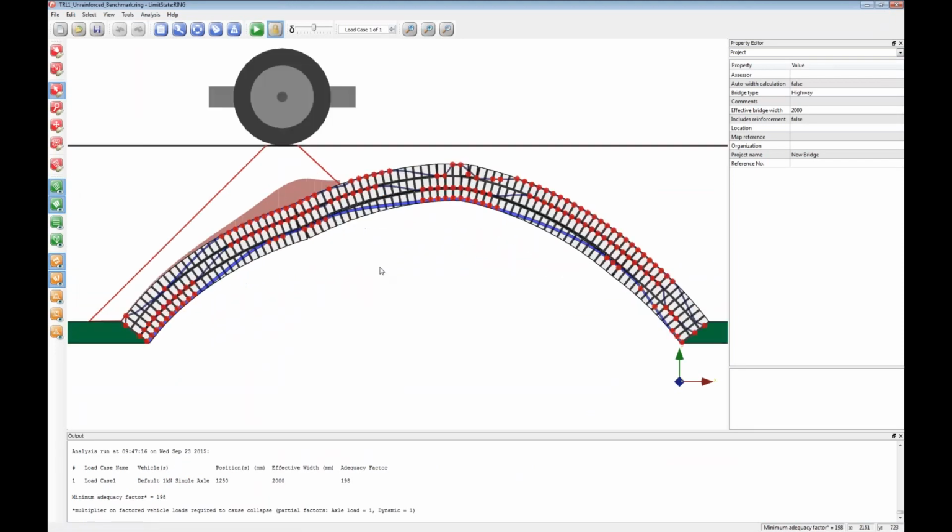Now this is clearly a multi-ring arch, so we've got relative movement between adjacent rings. We've got these diffused hinges that are characteristic of multi-ring arches, and we can see from the thrust line that the majority of the work is actually being done by the bottom ring of the masonry. So the question is, can we enhance the capacity of this structure by putting in reinforcement?